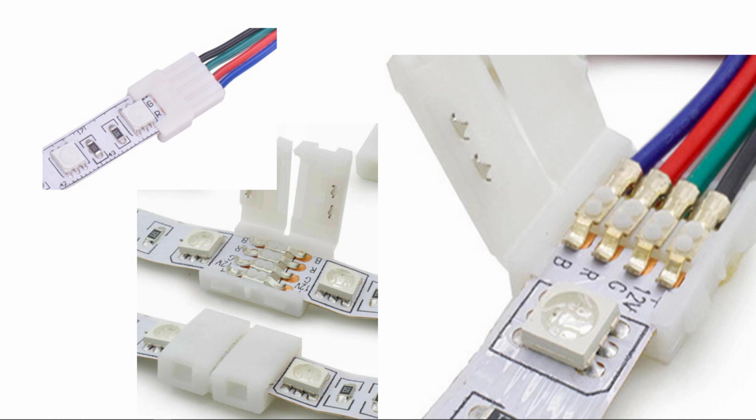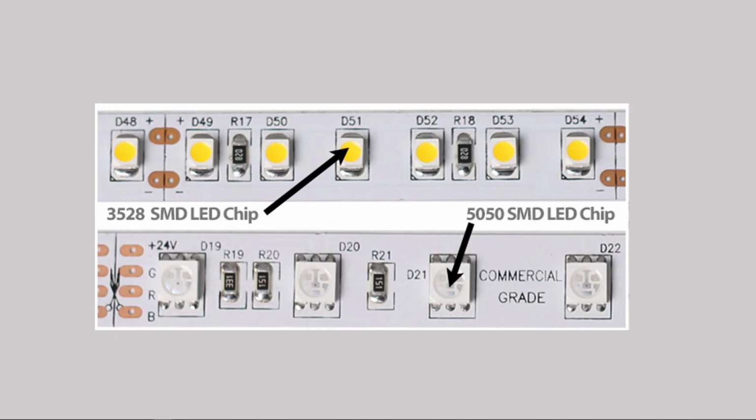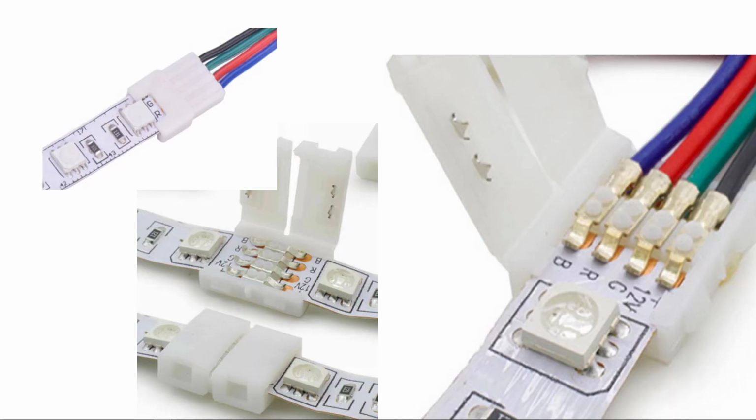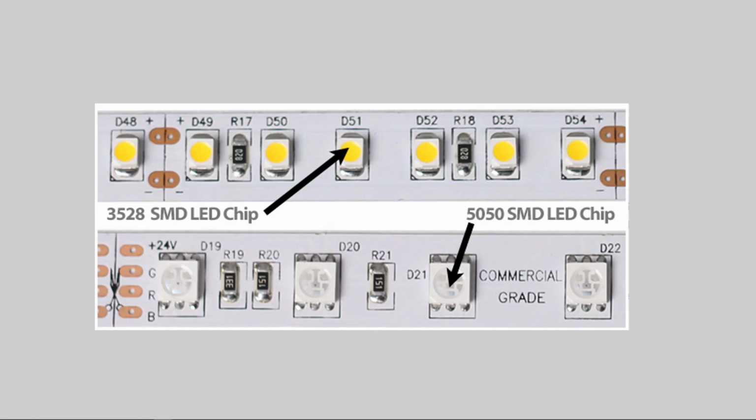That's something very important for you to know, that you attach the plus side of the power supply to that particular line, the black line, or it might be white. And then the current goes through the red, the green, and the blue through the LED back to the dimmer or the power supply. And by the way, these things come in all shapes. They come in T's and L's. Also notice when you close the clamp down, it's got some teeth on it that grab hold of that strip so it doesn't pull out easy.